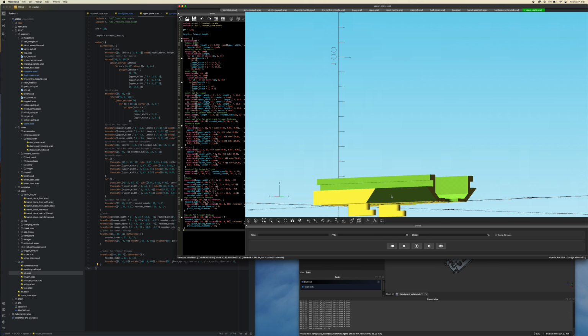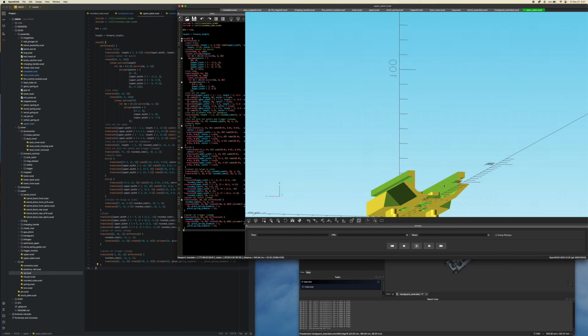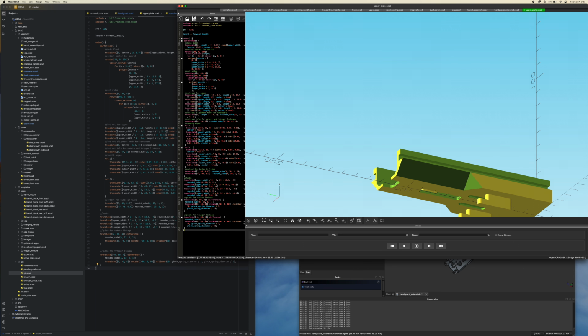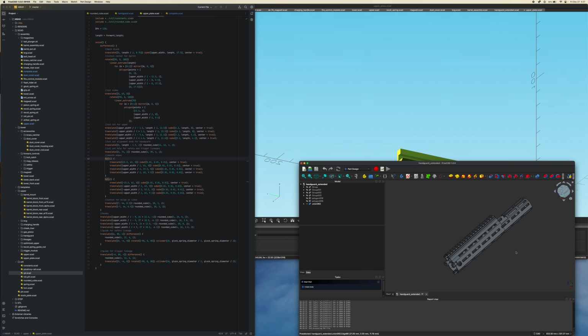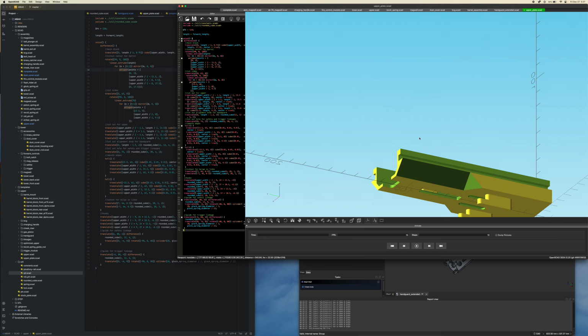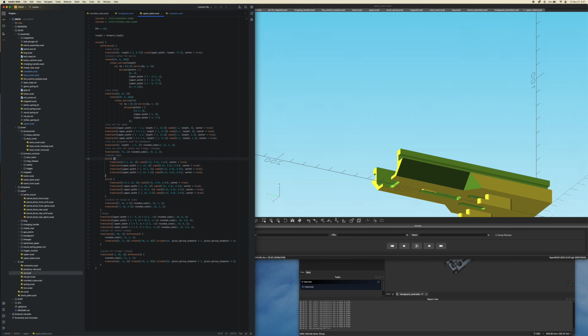Previously, I had an issue here where, if you notice, these two are symmetrical on both sides, so I did the same thing by mirroring, for example. I mirrored these, and OpenCascade did not like that for some reason. It works fine for the extruded polygons, but when you have a hull nested inside of it, it just really doesn't like that. So just be careful with that.